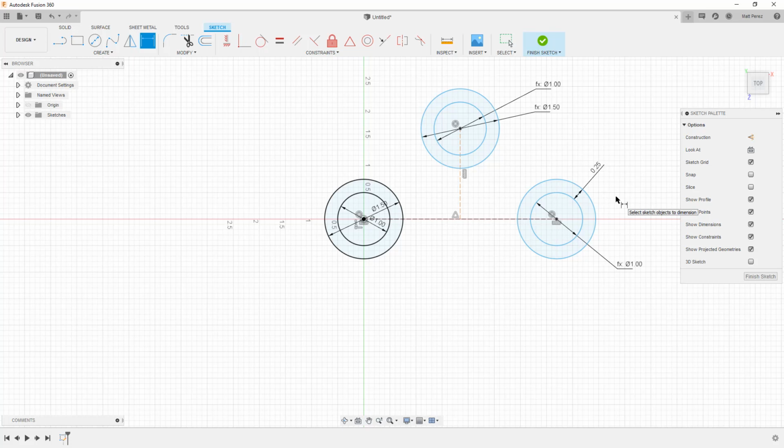I'm not going to say that there is a right or a wrong way to go about this, but there are certainly benefits and drawbacks depending on what you're modeling. If you have a design that is molded, for example, you're going to have a universal draft angle that you're going to want to apply. Maybe it's different on the outside if there's a texture. You're going to have a wall thickness that you want to use. You're going to have other values that are going to be consistent throughout the design.